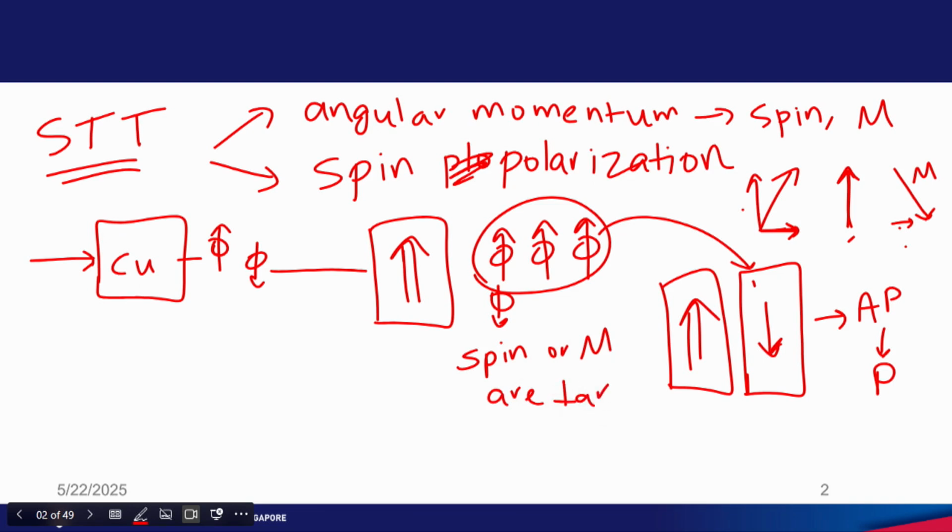So, I was always showing spin up, spin down electrons going this way, and this magnetization also is perfectly parallel. Okay. So, you may wonder how it can switch. When these two are completely parallel, there cannot be torque, there will be no switching. So, what happens when you operate MRAM, for example,